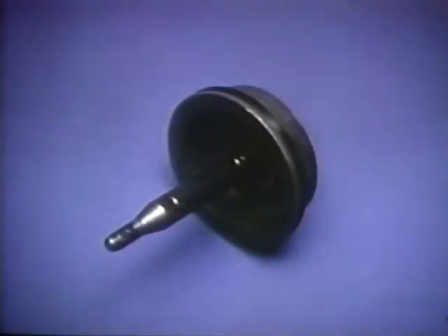The third component is called a brake band piston. The brake band drum is mounted to rotate within the brake band. The band is wrapped loosely so that the drum rotates freely. The brake band piston is placed at the open end of the band. When hydraulic pressure is applied to the piston, the band is compressed and locks the drum and prevents it from turning. The component of the planetary gear set attached to the drum is held, providing gear reduction.